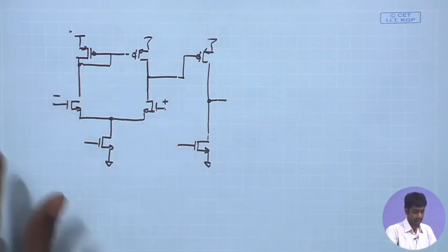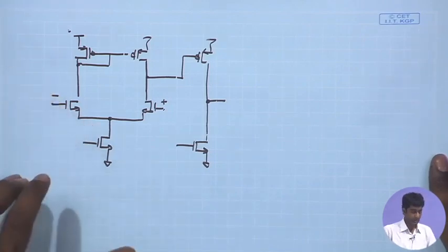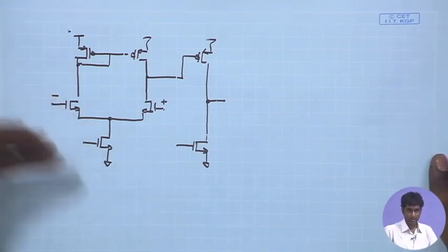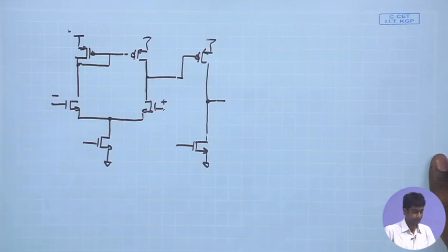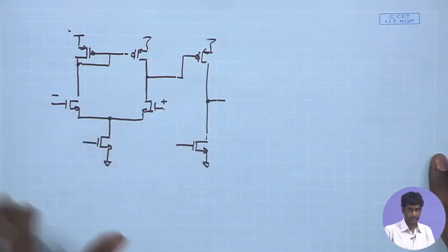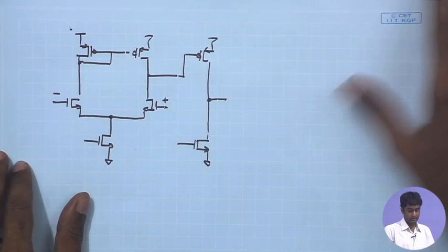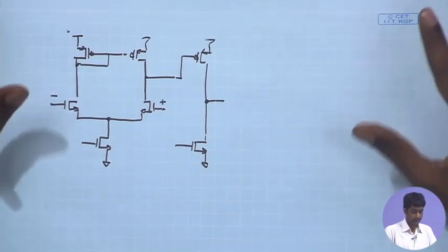And we noticed that if the resolution requirement of the ADC is even higher, maybe rather than 7 bit you are going for 8 bit or 9 bit, the resolution mandates that the offset must be addressed. If you have a few tens of millivolts of offset, it would corrupt a lot of LSBs, or in other words, the error in the data will correspond to a large number of LSBs. So, we would like to mitigate this offset using appropriate circuit techniques and look at the overall details of the circuit implementation.